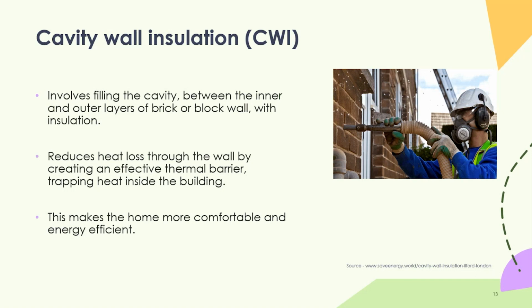Some of the risks around this are that you need to do a very good survey of the wall before you introduce material in there. The other thing is that quite often with these walls, where they have been filled with material previously, there are a lot of instances where water has got into the cavity, and because the material is maybe a porous fiberglass material, it's soaked up the water, and it actually then ends up almost creating a wet barrier, which creates problems.